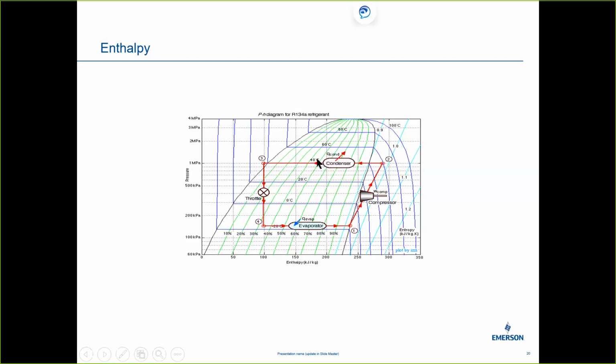It's just saying what the condenser does. We're rejecting the heat here. Notice we're in that 2-phase area, okay? We're going from our vapor to a liquid. And then we get down here to number 3 and we start to go vertically down. That's signifying our TXV, or our metering device.